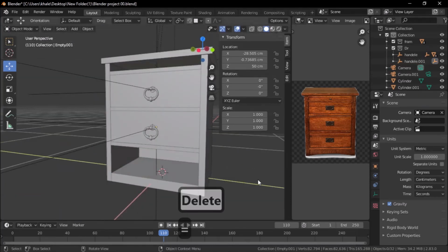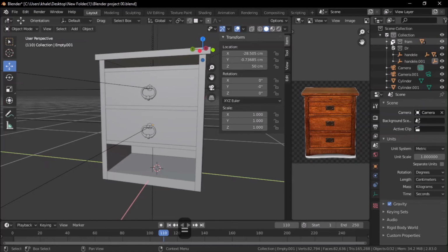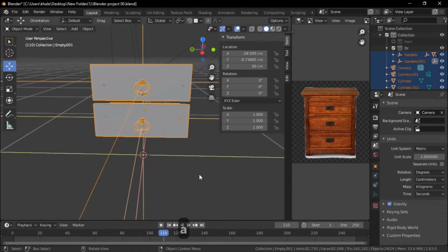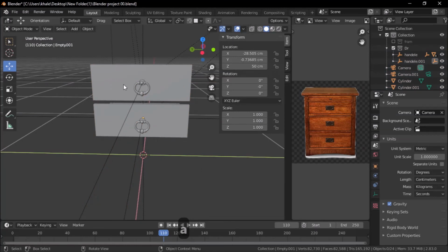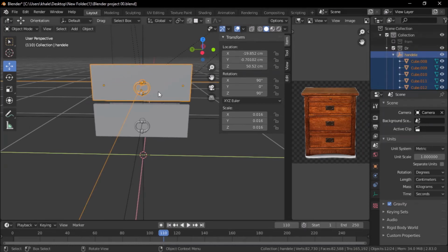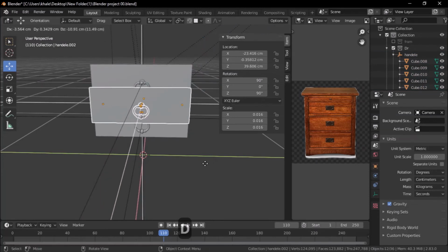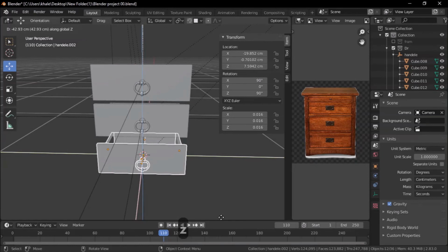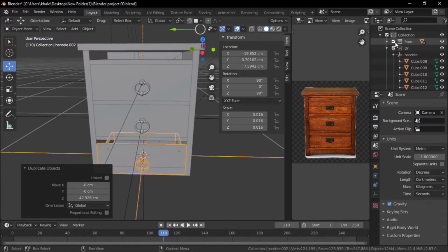Now let's duplicate the last one, hide the frame, and select the object. Now if I press the A key, I will select both objects, and I only want to select one. So to do this, go to the outliner, left click this one, and select hierarchy, and you will select one object, and as we learned before, shift D for duplicate, Z to move in the Z axis. You can also enable the X-ray so you can select objects behind objects, but that's much easier.